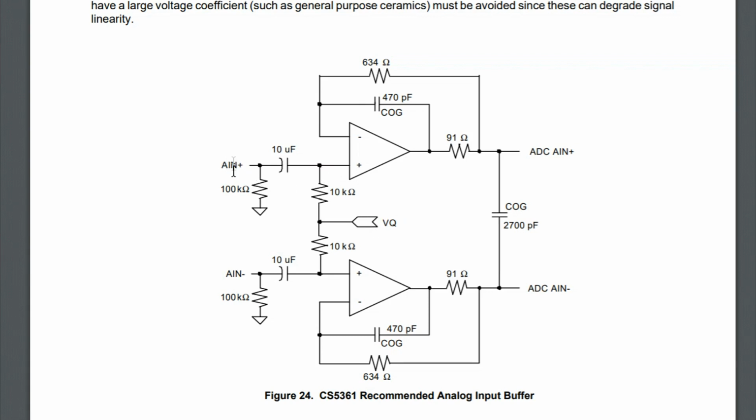So what we have here is, right, the signals are going to come in, a balanced signal here. It's going to swing around 0 volts, and then we have a coupling capacitor here, and then we change it to swinging around 2.5 volts, so half the supply voltage of the op amps and the AD converter, and various filters. So I think I would like to try to build a new front end, something very similar to this, and let's see if that improves the performance.